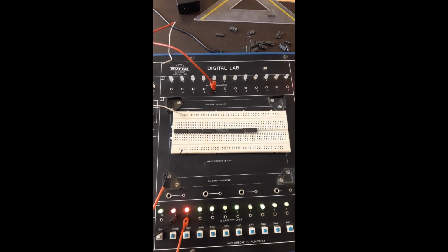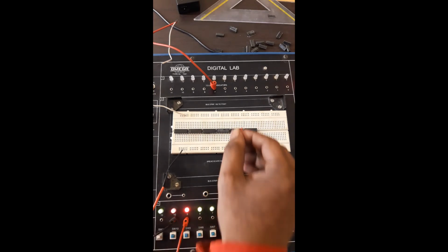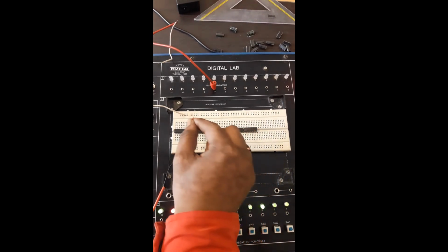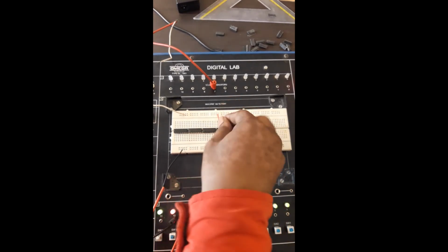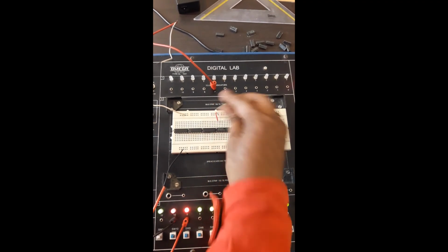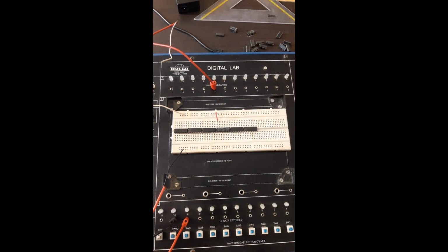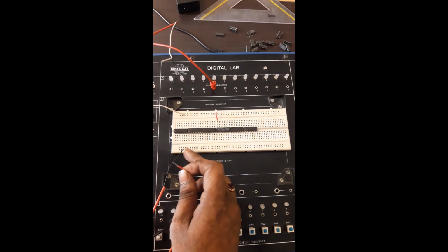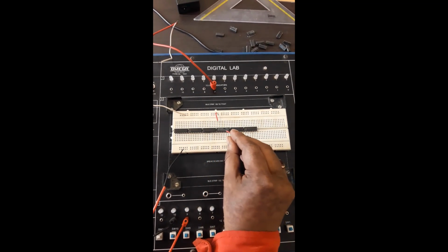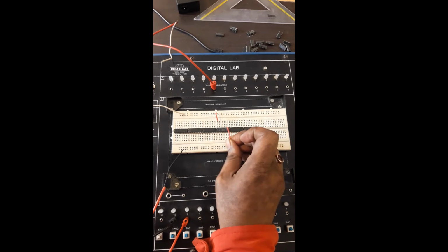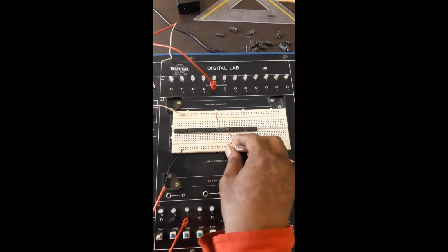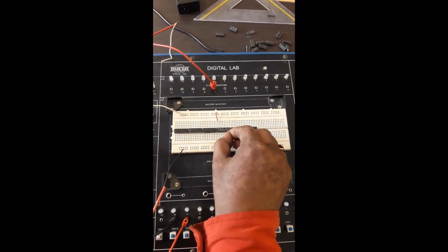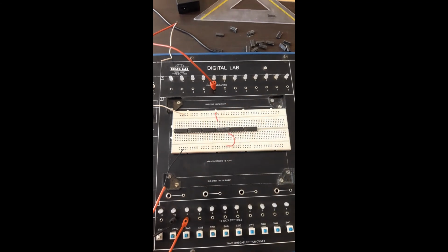So we need to give the power supply. For that we need to connect the VCC with pin number 14. So this is pin number 14: 1 2 3 4 5. So we can connect like this way. So now pin number 14 is connected with VCC. Let me switch off the device. And then we need to connect the ground also. So 1 2 3 4 5. So we can connect the ground terminal from here to pin number 7. So we have connected the plus VCC and ground with the IC.